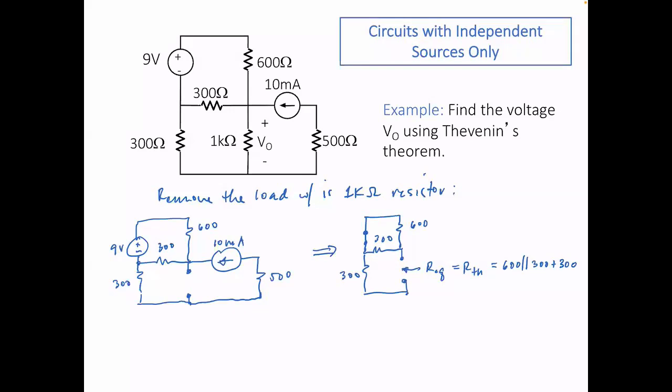Okay, how do you get the Thevenin voltage? The Thevenin voltage is the open circuit voltage across the load terminals. So this is your Thevenin voltage, VTH. We'll assume that it has that particular polarity. The way you get Thevenin voltage, nasa sa inyo na ngayon. It's up to you.